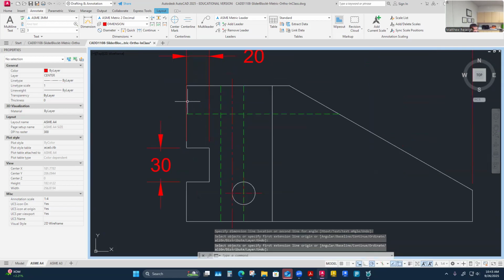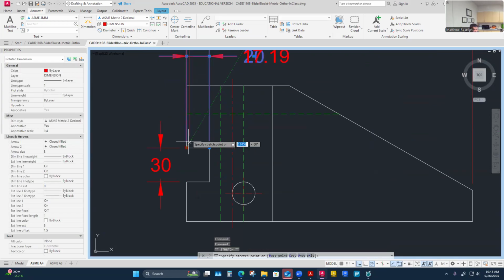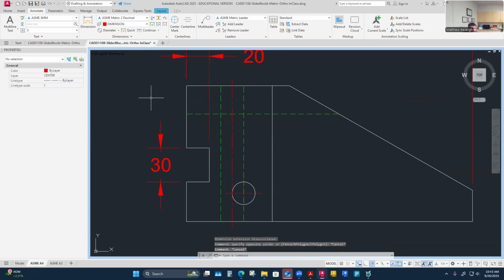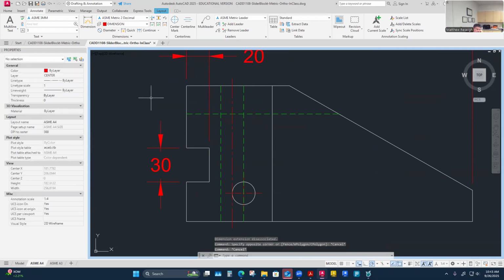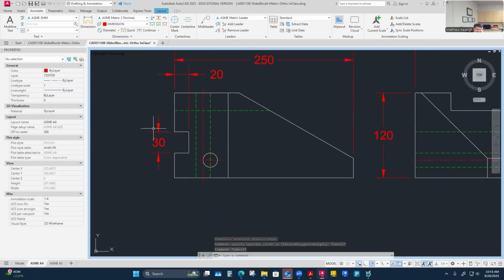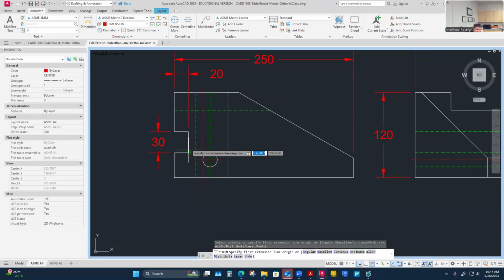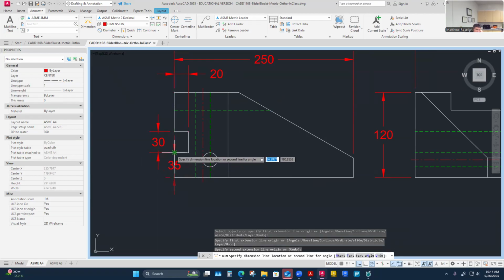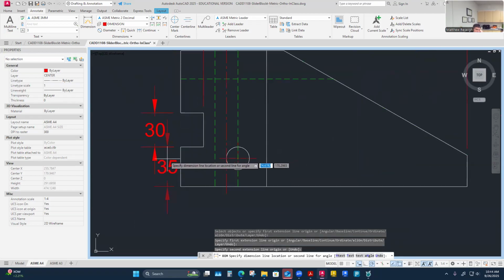I don't know if it's going to be the intermediate one. And technically I need to pull these back to the object edge. That one's going to stay down and across because I've got to reach out over to it. That's its size. Now its location is up some distance, and it needs just one dimension to locate it. It's just up. Since I've got the size in this view, I think I'm going to use where it lives right here. It's 35 up to that first notch.